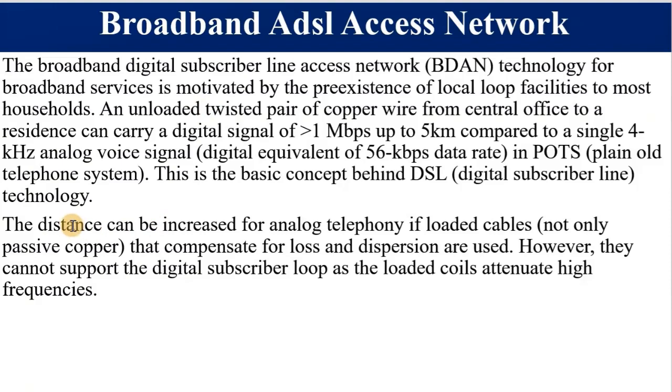So we are saying the distance can be increased for an analog telephone line for voice alone if we load cables. This helps to compensate for loss and dispersion. However, they cannot support digital subscriber line as the loaded coils attenuate high frequency signals. You can find out from inductive reactance, XL equals 2 pi FL, meaning the higher the 2 pi FL, the higher the inductance, the more the inductive reactance. Please take note.